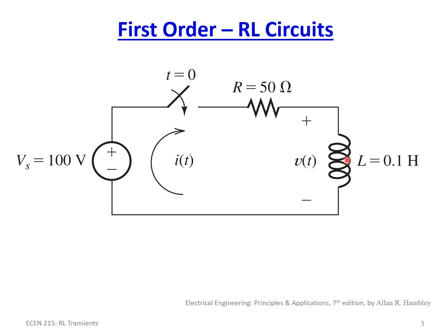In fact, it's going to have a very similar reaction, but the circuit analysis is slightly different because, if we remember, inductors work off of current, and they prefer to have a constant flow of energy, constant current, because the energy in the case of an inductor is stored in the magnetic field, versus in a capacitor, the energy is stored in the electric field. So here, the inductor wants to maintain the magnetic field going through it, and as the current is changed, it alters the voltage across the inductor. If you can kind of imagine here, we've got this I of t going through the circuit, and we're going to apply an analysis to determine what V of t is across the inductor.